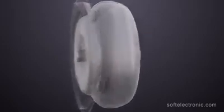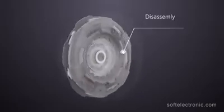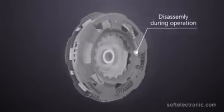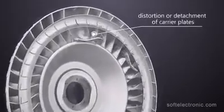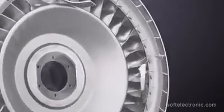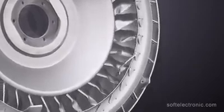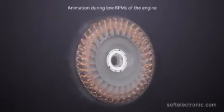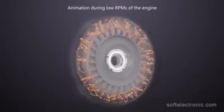There are also cases where, due to untimely or poor repair, the damper can be disassembled and the gearbox may be blocked. Under such conditions, a turbine blade or the pump may break, which begins to circulate freely in the fluid flow. This can seriously damage the components of the torque converter. If there's a problem with the one-way stator bearing, this can have a serious negative effect on the flow control between the pump and the turbine.